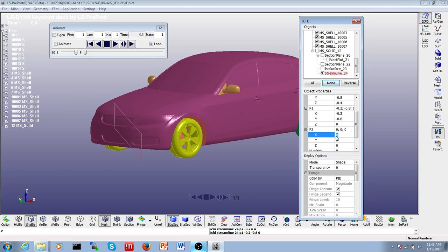You see that as I'm doing that, on the left of the screen, it's drawing the plane from which the streamlines will be generated. Okay, and then here you see it's red again. That's because all of this hasn't been taken into account yet, because it first lets me pick how many streamlines I want. Let me see, I have 10 by 10. Okay, that'll be 100 streamlines.